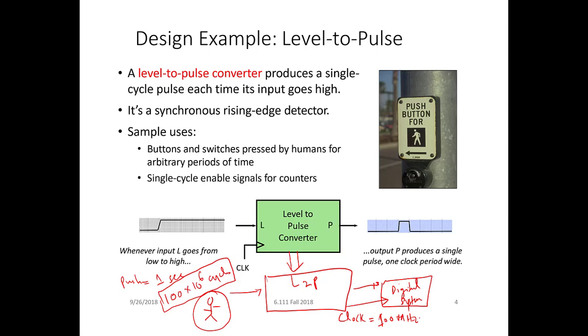And what this device does, it is a very interesting device, that if you have this kind of level, so this is a level input, what this system does, it takes the same 100 megahertz clock frequency, but it converts this level input to a pulse that is exactly 1 T clock. That is exactly 1 time period. How can we develop this interesting system?